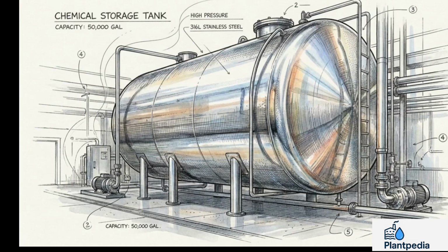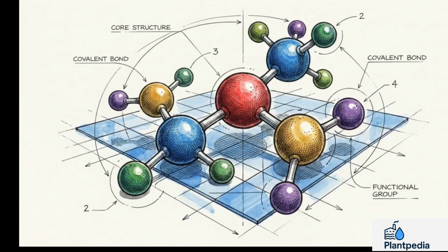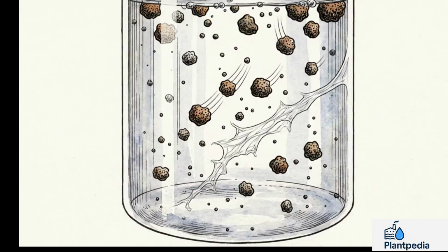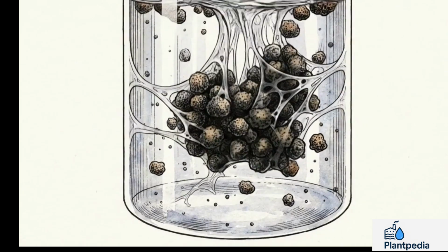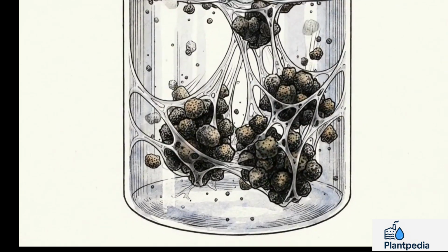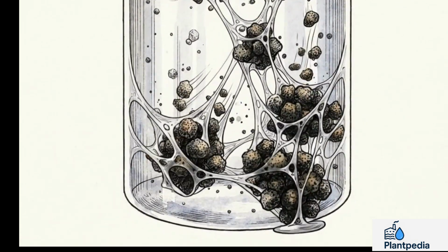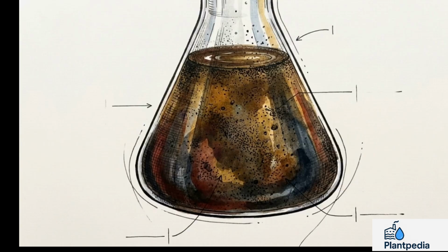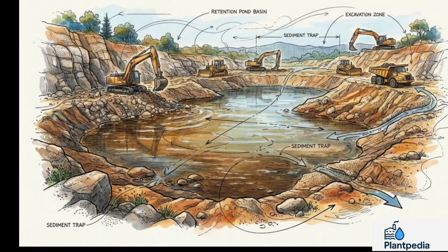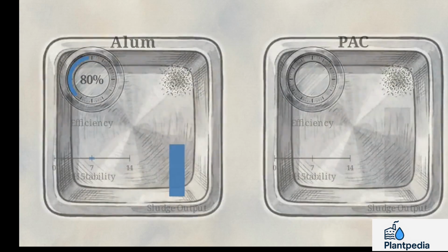This brings us to polyaluminium chloride, or PAC, which operates as a high-performance, modern upgrade to the traditional alum baseline. PAC works by rapidly forming floc, the process where microscopic suspended particles bind into dense clusters that settle out of the water column at high speed. This speed makes its target applications heavily industrial, specifically treating high turbidity water, vehicle wash water, and industrial surface water.